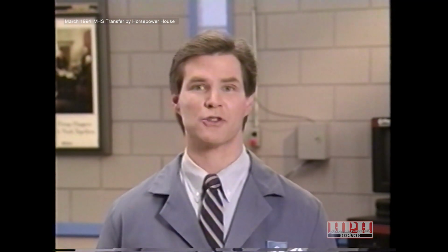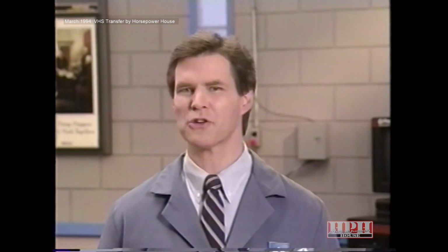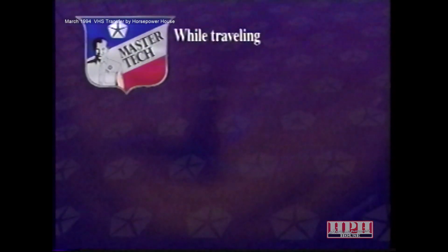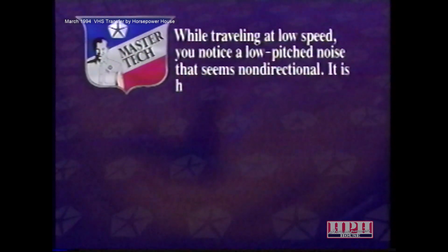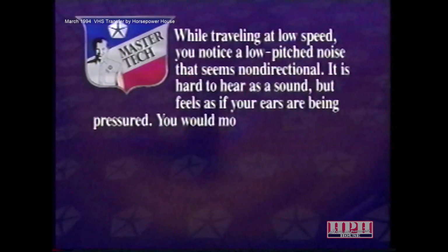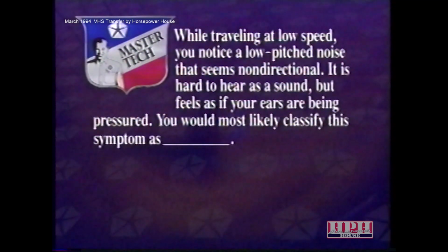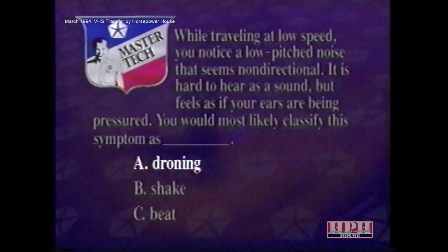As we've seen, effectively classifying a vehicle's NVH symptoms enables you to isolate the root cause of the trouble. Let's make sure we can effectively classify before we go any further. While traveling at low speed, you notice a low-pitched noise that seems non-directional. It's hard to hear as a sound, but feels as if your ears are being pressured. You would most likely classify this symptom as A, droning, B, shake, or C, beat. A, droning is the correct answer. Let's proceed.